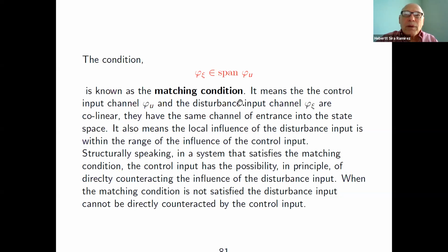But of course, engineers are very smart, and the trick that they play is that they suppress the electrical dynamics because they say it's much faster than the mechanical part. And therefore, they establish an algebraic relation between the input and the mechanical part, represented by the angular velocity and the torque constant or the electric constant. And with that algebraic relation, they substitute into the second equation, and now everything is matched.